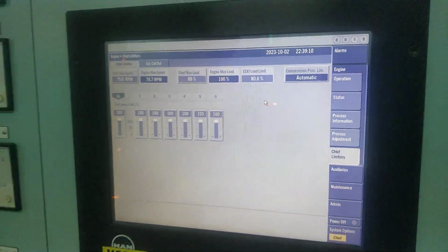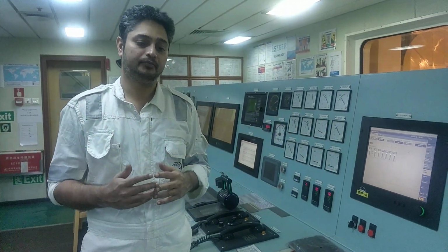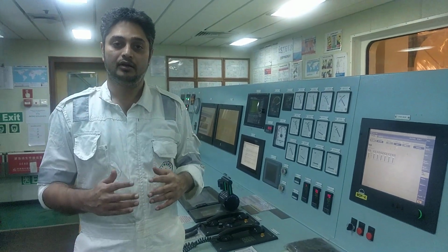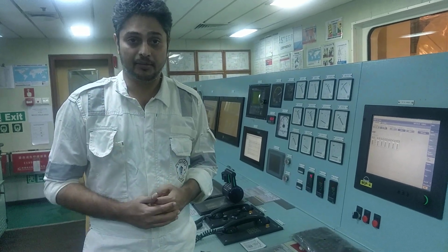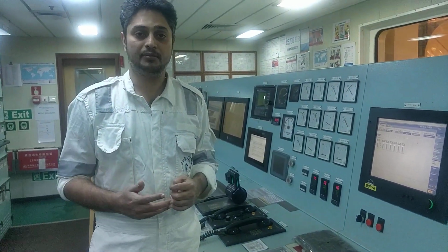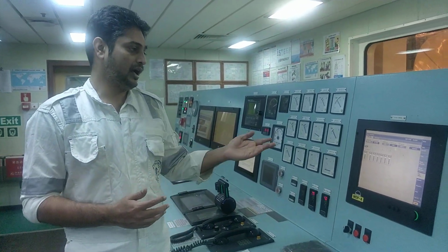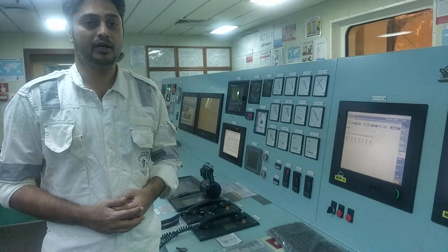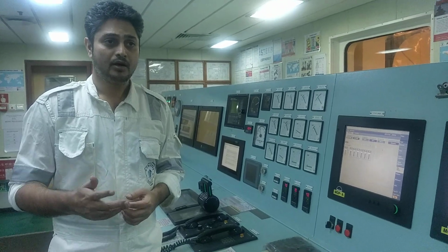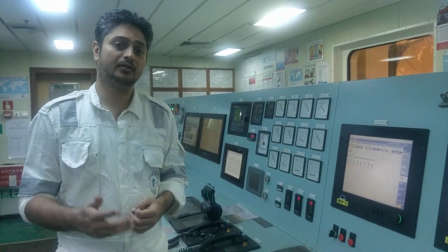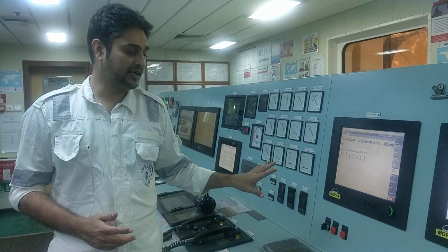Indirectly this means my MCR, I have to assume, is actually 80.6% of the original MCR. My original MCR of this engine is 15748 kilowatt, and after EPL installation it is 12792, 80.6% of the MCR as per the yard. Okay, so this is about the setup.